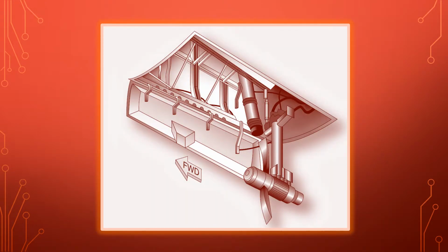Hydraulic motors, or ram air turbines, may also be incorporated into this system to provide redundancy in the event of multiple failures. Essential AC and DC components are wired to specific buses, and special provisions are made to provide power to these buses under almost all failure situations. In the event that all AC power generation is lost, a static inverter is included in the system so the essential AC bus can be powered from the aircraft battery.